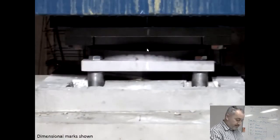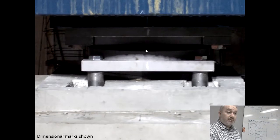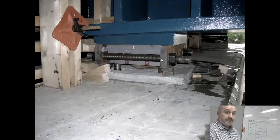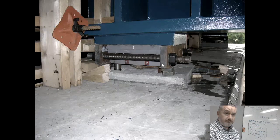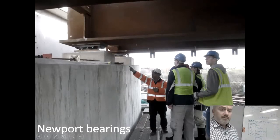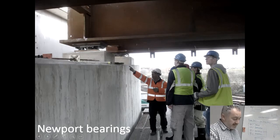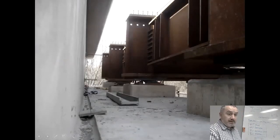And these are pot bearings. They're the most common type of bearing that are used on bridges. So this is the pot bearing. And this is the Newport bridge. We took the first year students to have a look at this. But yeah, this space is so that they can jack up the bridge and replace and maintain the bearings. And then it's grouted up with a high strength grout.